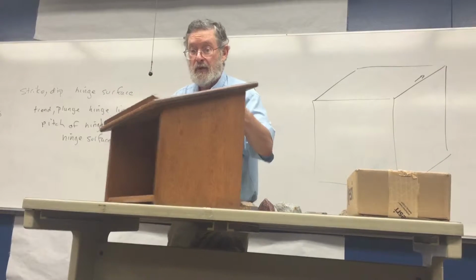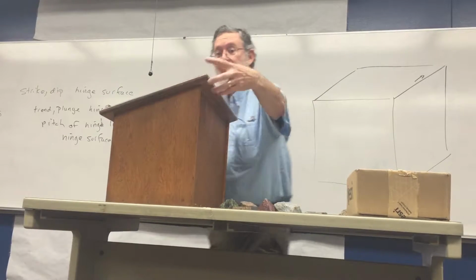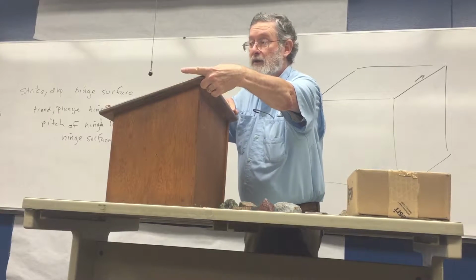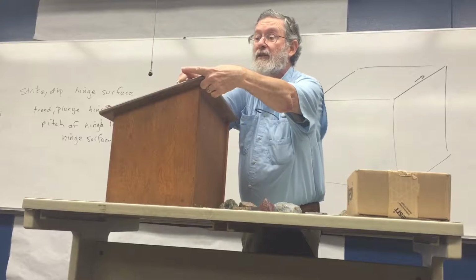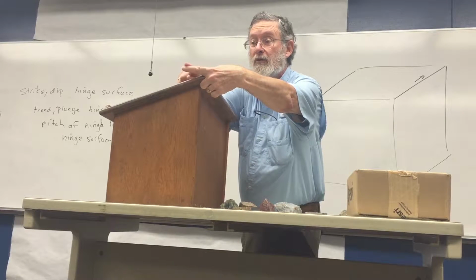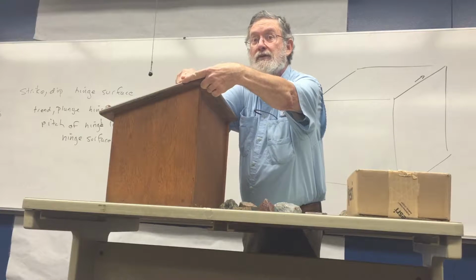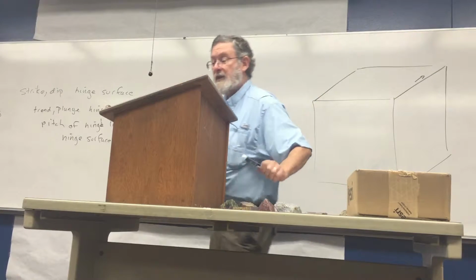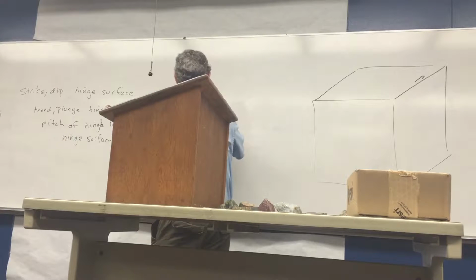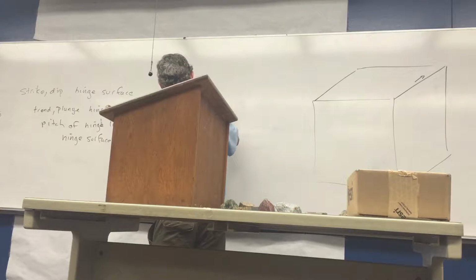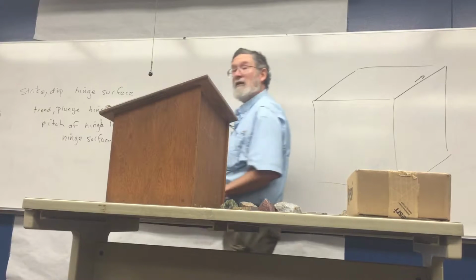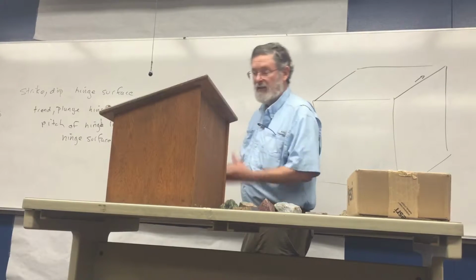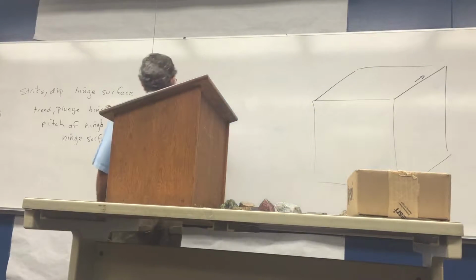The dip, if we look on edge, is this angle that is measured perpendicular to the strike, and it's this vertical angle from the horizontal down to the plane. The way that we denote that is we would have this sort of symbol, and we would write the dip angle here. And this dip looks like it's about 17 degrees.